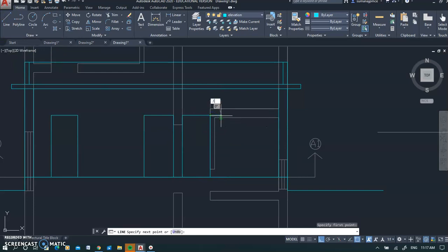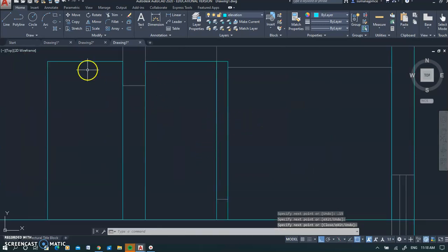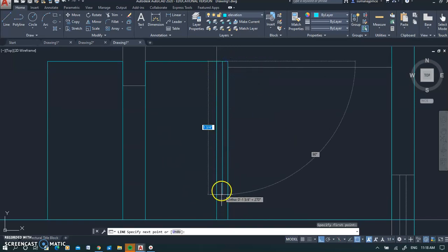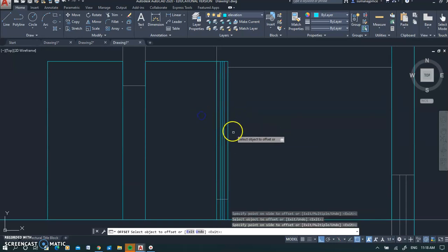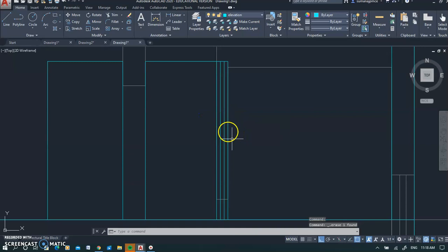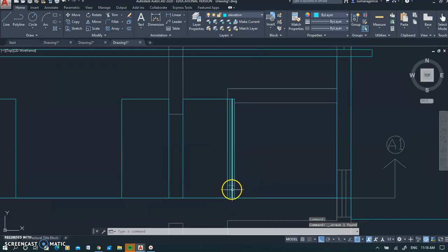So we come this side by 0.15 and this door is cut. So you see the frame of that door which is cut, and so you need to draw the frame inside, for which we can take a center line and offset it by a distance of 0.025, half the size of the frame, and then offset it on this side, offset it on the other side, escape and remove the center line. So you see the door, this door is cut in section.